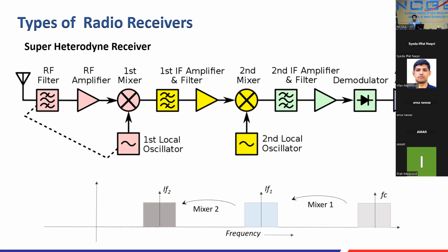In all frequency translation devices, where receivers translate from one band to another, the mixer is one of the key components of your design. If you don't pay much attention to the selection of a mixer, then eventually your information will be lost. You might have spurs at the later stage. You might have intermodulation distortions. So selecting a mixer is also a big challenge.